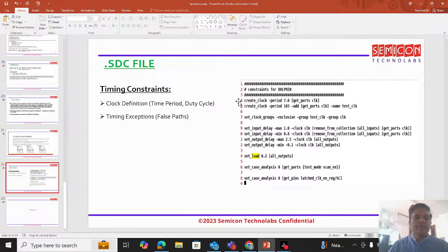Now this way we are getting the initial timing constraints file from the RTL team, and then based upon the other parameters which we give during the synthesis with respect to timing constraints, it can be design margins like uncertainty, derates, max transition, total area which we need to achieve, input delay, output delay, set driving cell, set load, set drive, right?